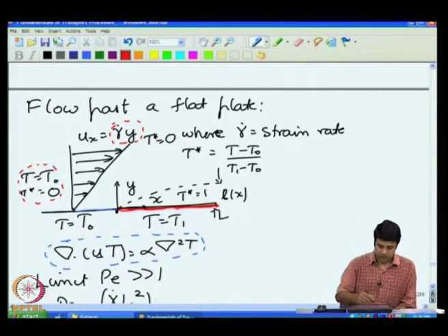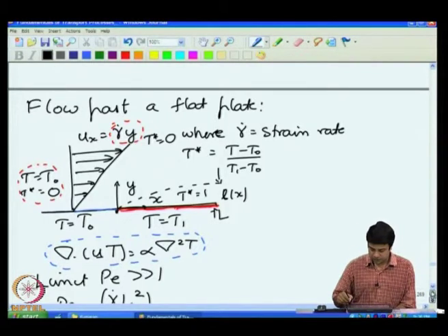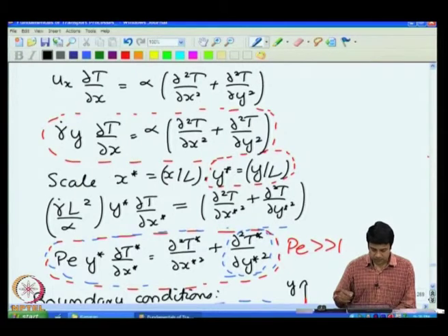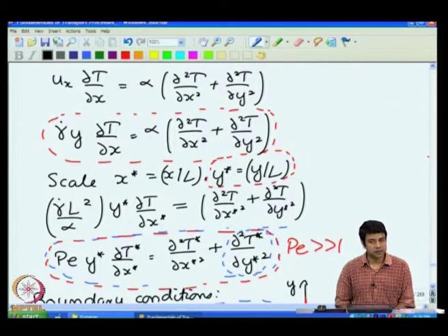The problem was that when we neglected the diffusion terms, the equation was converted from a second order differential equation to an ordinary equation. For a second order differential equation in y, there are two boundary conditions. For an ordinary equation, there are none. And since we do not have constants in the equations which emerge from the integration of the differential equation, we were unable to satisfy boundary conditions.